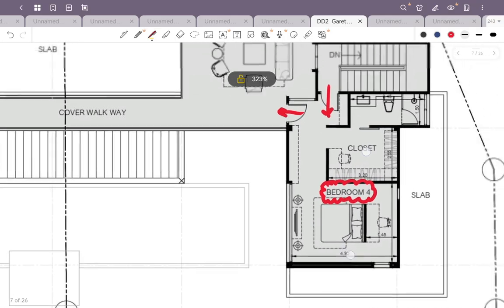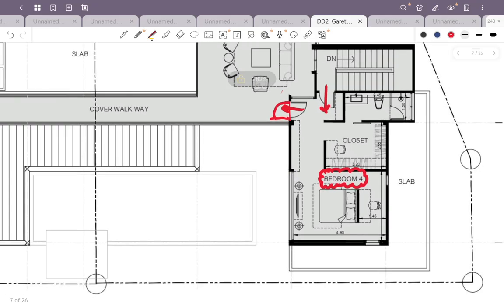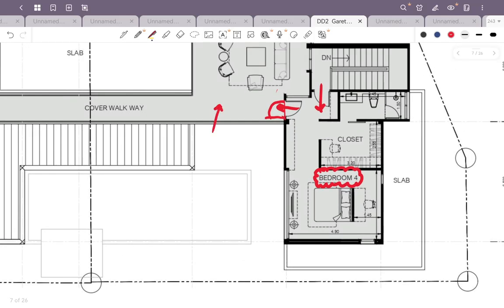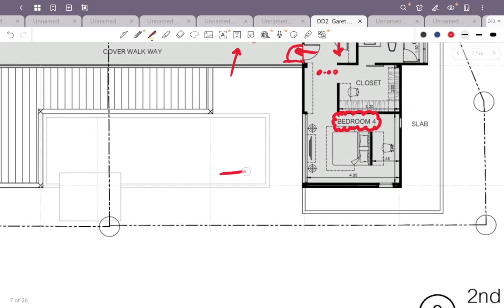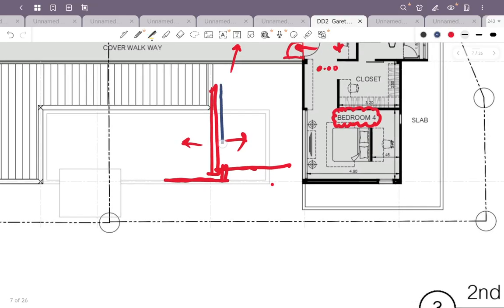Okay, then next, normally if you have a door that opens to the outdoor, you need to open outwards, otherwise the water will flow inside. Just imagine the floor level of this covered area will be 10 centimeters lower than here, right? So the floor should be like this for the section. So the door should be here, which means it cannot open inside but has to open outside. But if you open outside, that means you install the door here.